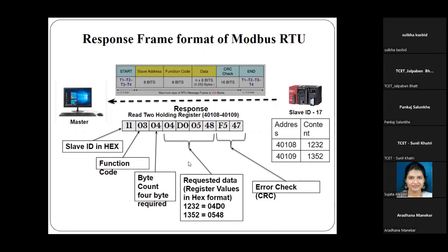So all of you have these two software, ModScan and ModSim. ModScan software is your master software, which reads the data from the slave, and ModSim software is just like a slave, which responds to the master. That's why I'm giving these two software for demonstration purposes.